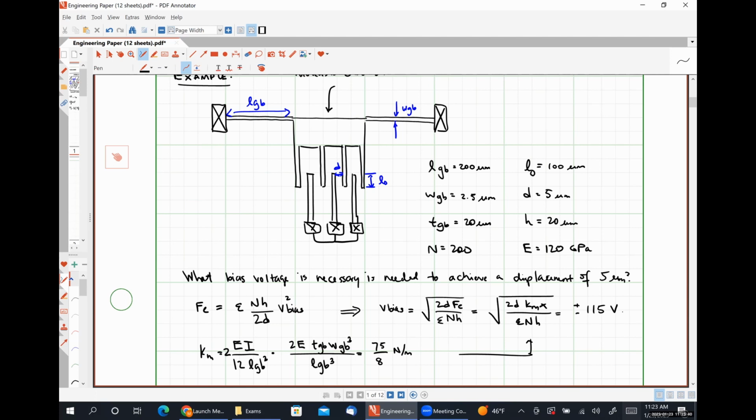When we talked about the gapped tuned devices on Friday, we observed that the maximum capacitive tuning ratio was effectively 150%. So we could never get more than a 1.5 increase in the initial capacitance versus the actuated capacitance, assuming that we were trying to avoid pull-in effects.